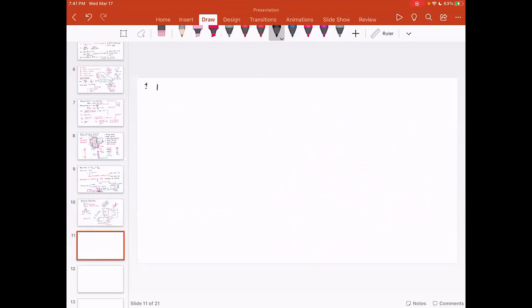So the pitch cone is the cone containing the teeth. When we look at the bevel gear, to cut a bevel gear you have to start with a cone, and then the cutter will continuously cut the teeth on the bevel gear's blank.